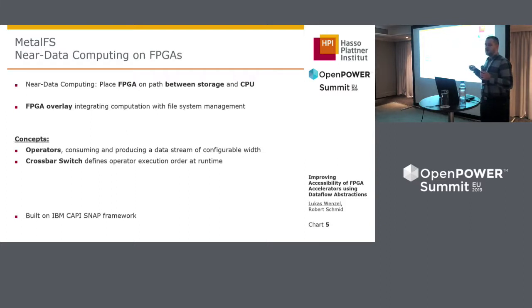And to make these resources on the card available, we, on the one hand, provide an FPGA overlay, which is just some kind of template architecture where you can define your functionality in a very fixed framework that allows you to avoid re-implementing all those kinds of usual operations like fetching your data and having to determine where you want to put it and so on. So you just focus on the computation part. And this is the role of operators. So an operator is some kind of piece of hardware that is closed in itself and takes one incoming data stream and produces one outgoing data stream.